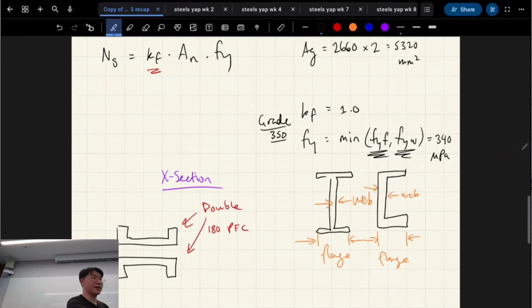You're gonna find that the thicker your section gets, the lower its yield strength gets. So imagine you pour a meter by a meter by a meter, so like 1 meter cubed of molten steel, right? And you just let it cool, right? And you're trying to use this structurally. Do you reckon that that's all gonna evenly be cooled? Probably not, right? So when you have something that's thinner, it's gonna have a more consistent yield strength. You have something thick like that, its yield strength can be poor because it didn't cool properly, basically, right? And so that's where you get differences in like this and this based on the thickness. So the thickness of the flange and the thickness of the web are different. Got it?